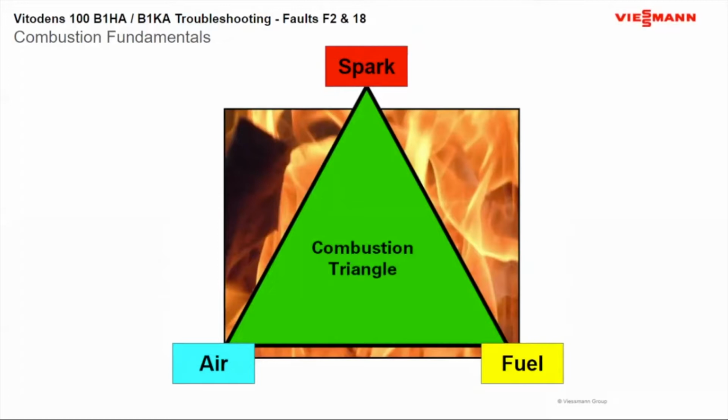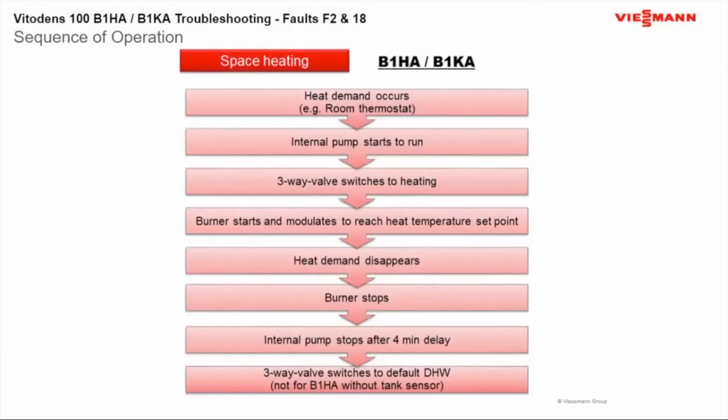So like I was saying, just go over this again. Remember your basics: air, spark, and fuel. That's your combustion triangle. So sometimes we tend to forget that if we don't have enough air, you know, we're going to get a fault. So or not enough fuel, or if we're not getting a spark. So sometimes we tend to forget about that triangle we learned in our tech schools.